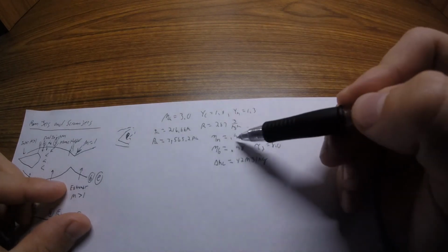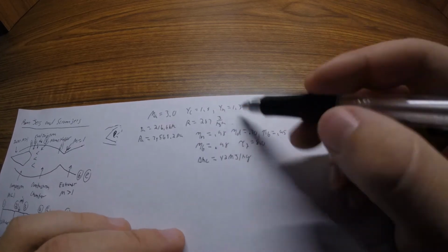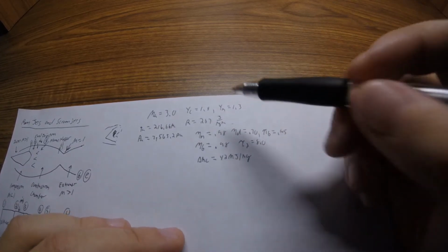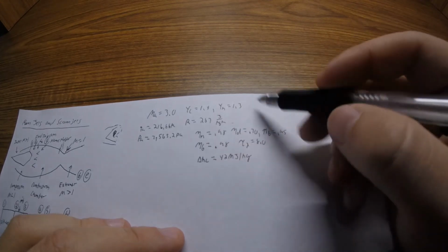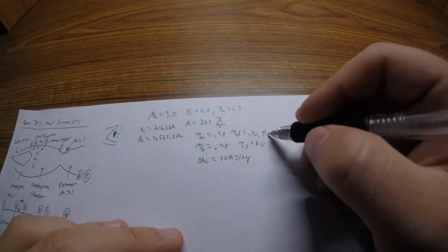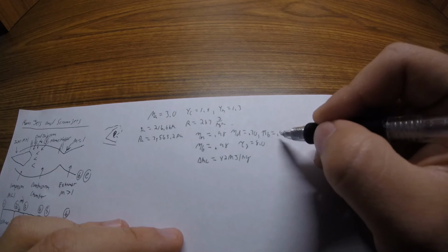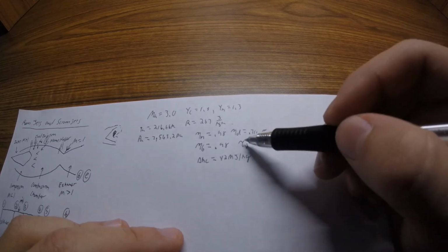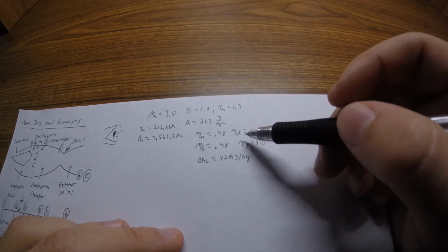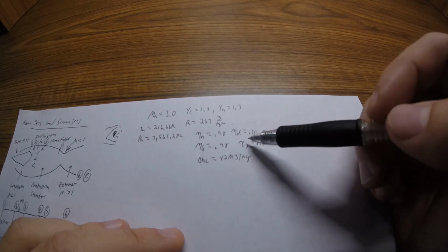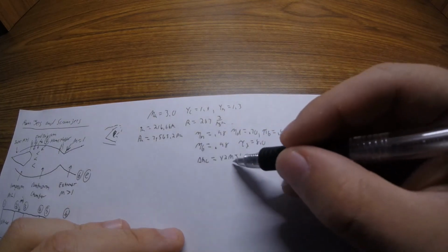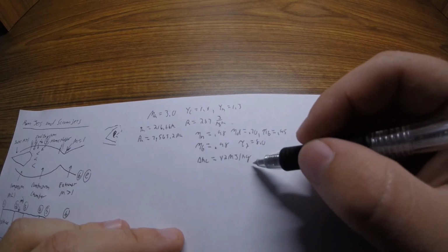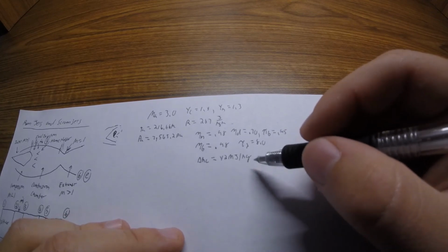Efficiency of our nozzle is 0.98. The efficiency of our diffuser is 0.70. And our efficiency of the burner is 0.98. The pressure drop of the burner is 0.95. The temperature relationship between state 4 and the atmospheric temperature is 8. And our heat of combustion is 42 megajoules per kilogram.